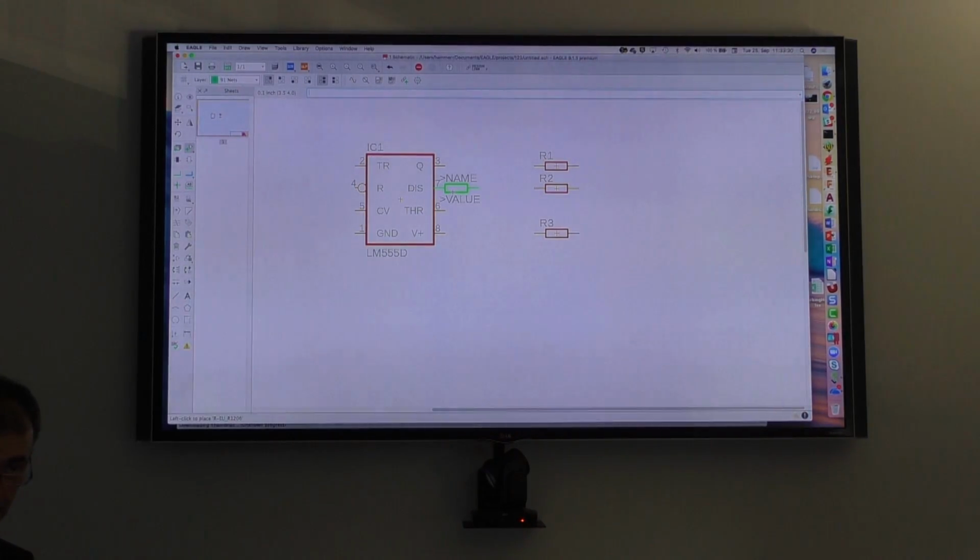I want to connect this pin with that pin, and therefore we need a second command. It's the net command. This one. If I click on it, I don't stop the command, I simply click the next command. And then if I approach one of these pins, these electrical connection points, you see a green dot. This green dot indicates where you have to start the net. By the way, meanwhile, it's the only point where we can start the net.